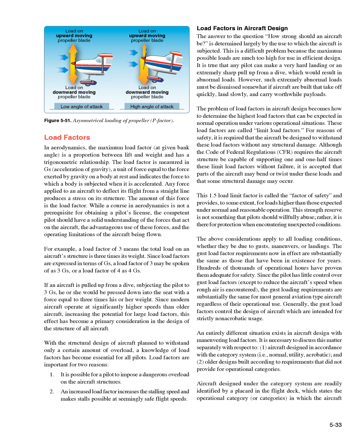This strength reserve is not something that pilots should willfully abuse, rather, it is there for protection when encountering unexpected conditions. The above considerations apply to all loading conditions, whether they be due to gusts, maneuvers, or landings. The gust load factor requirements now in effect are substantially the same as those that have been in existence for years. Hundreds of thousands of operational hours have proven them adequate for safety.